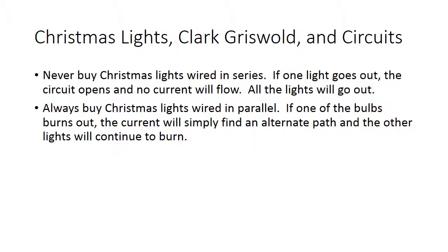So he puts them all up, hammers them up all over his house. But when he plugs it in, nothing happens. Well, the problem here is that he bought a string of lights wired in series, and so if one of the bulbs is burned out, it's going to open up the whole circuit, and none of the lights will light up. And that is the problem with buying Christmas lights that are wired in series. If you don't want to spend hours and hours looking for the burned out bulb, always buy Christmas lights that are wired in parallel.